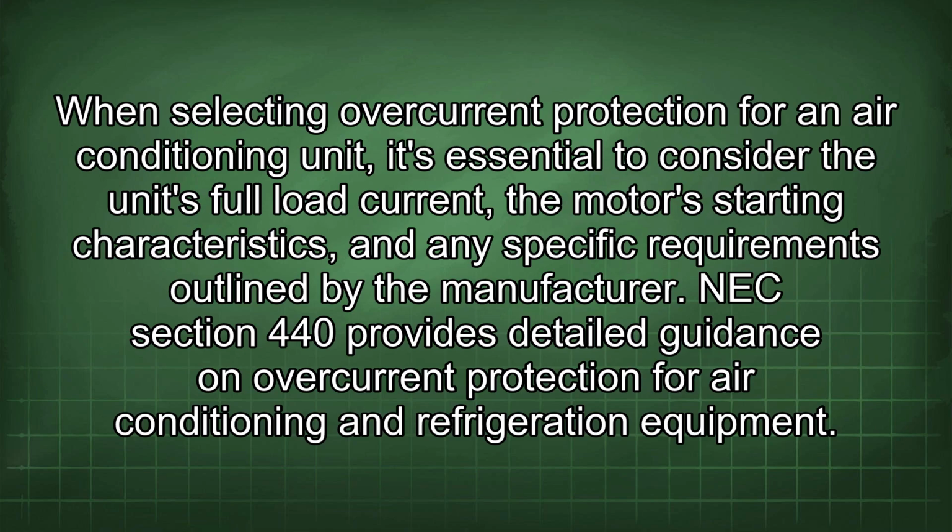When selecting overcurrent protection for an air conditioning unit, it's essential to consider the unit's full load current, the motor's starting characteristics, and any specific requirements outlined by the manufacturer. NEC Section 440 provides detailed guidance on overcurrent protection for air conditioning and refrigeration equipment.